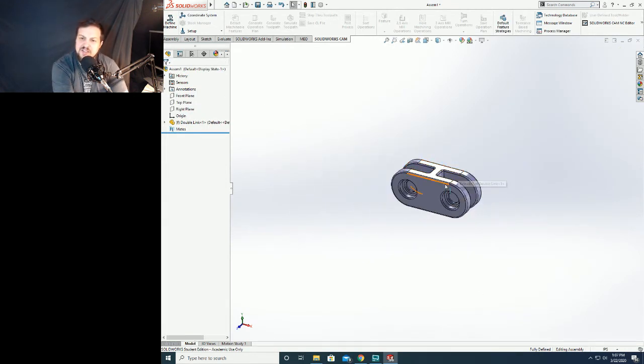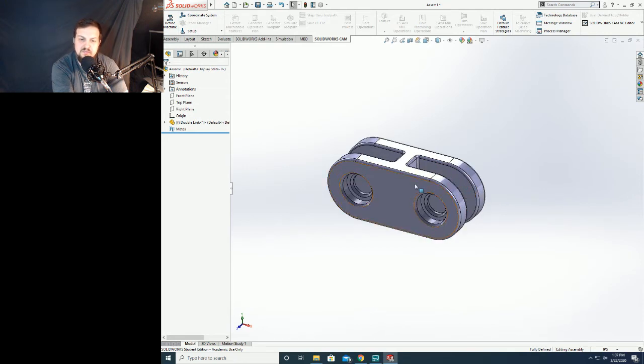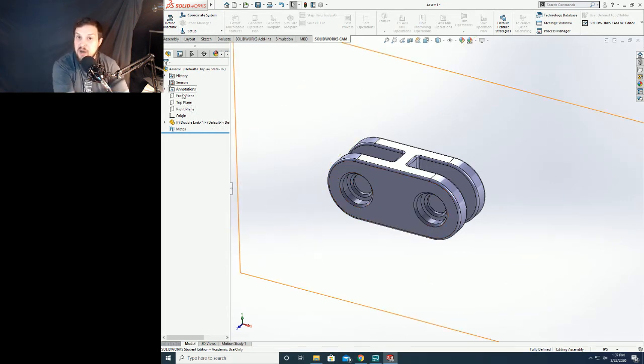Now the location that it put it is directly over the origin. So what it does is it overlaps the origin of the component that you've created and the origin of your 3D space that you're working with in your assembly. So now this component is perfectly overlapping the origin in our assembly space out here, because if you look over here on the left, this is now our model tree, not our feature tree. And there is a distinct difference.